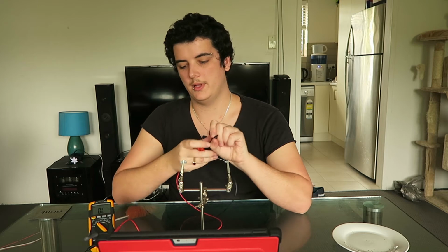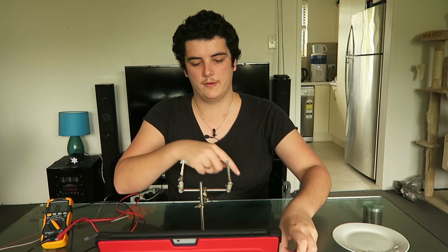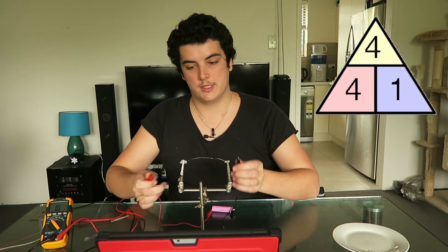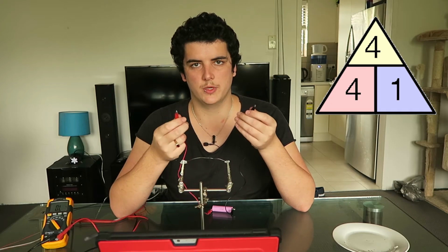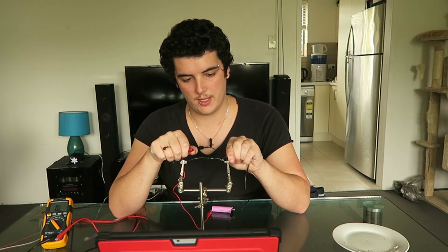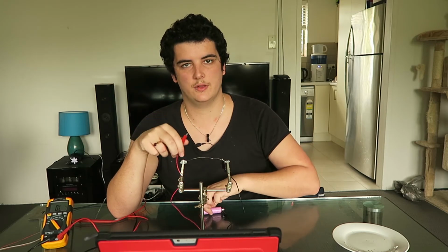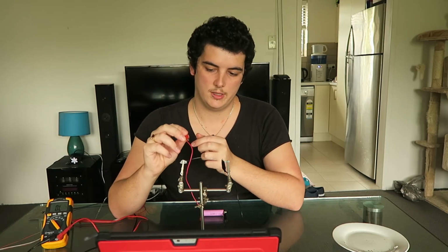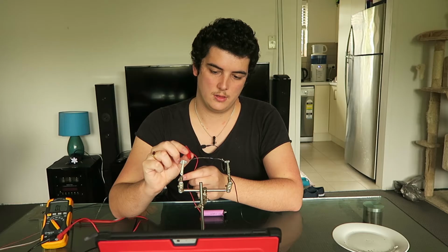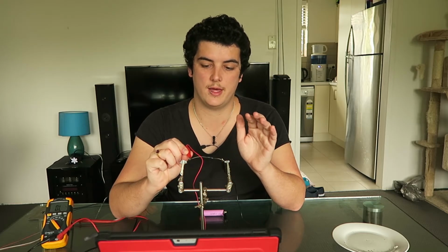Therefore, if we apply a 4 volt supply to that, how much current are we going to get flowing through this wire? Well, it's the exact same circuit as the one simulated, right? So we should get 4 amps of current flow. Attach this wire here. We have our 4 volt supply, which is the 18650 cell, not fully charged, so it's 4 volts from the previous video, and we attach this here, and that's really hot. So there's current flowing through that.